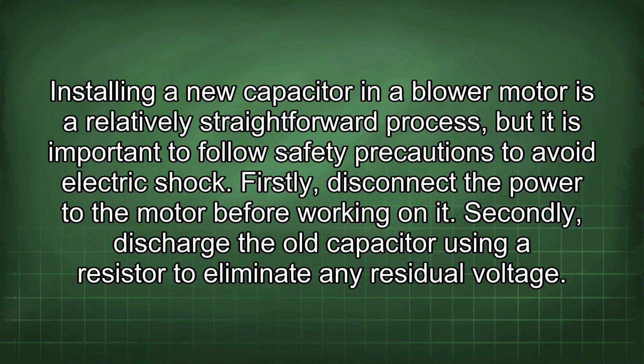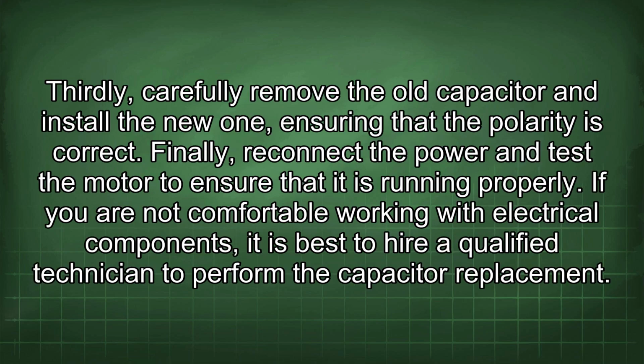Secondly, discharge the old capacitor using a resistor to eliminate any residual voltage. Thirdly, carefully remove the old capacitor and install the new one, ensuring that the polarity is correct. Finally, reconnect the power and test the motor to ensure that it is running properly.